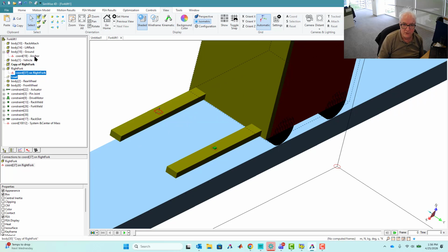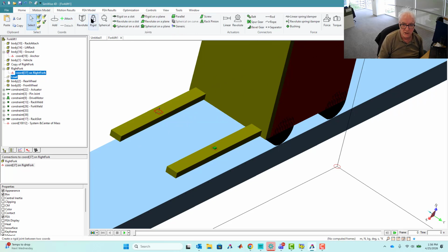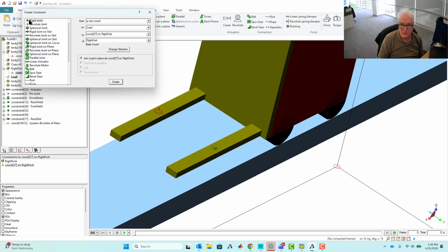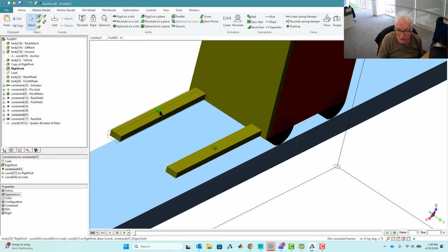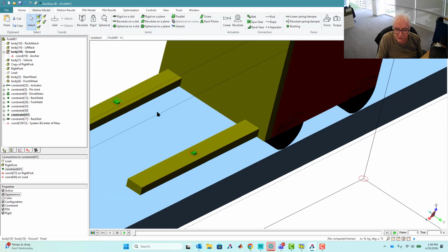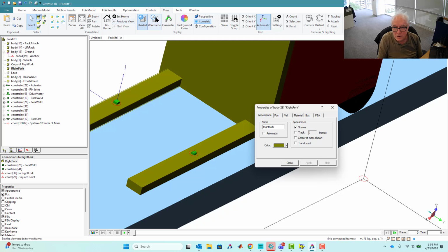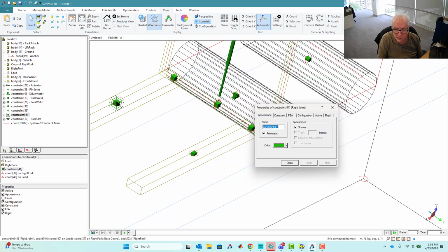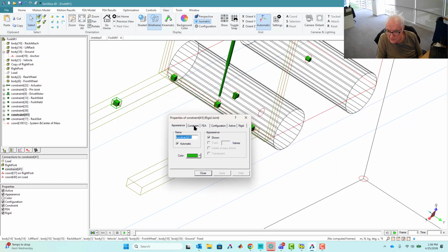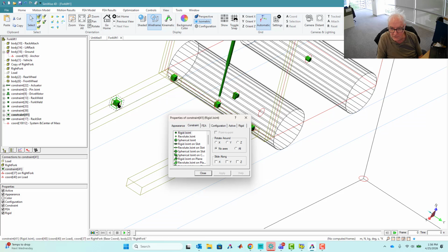So anyways, with those two selected, let's go motion. And again, I like this idea of creating a rigid joint because it gives you a good starting point. And so again, let's get it maybe to there. All right. And actually, this is what I'm going to do this time. View, let's look at a wireframe, and you'll see all this really well this way. All right. And so that constraint's right there, and we're going to allow it to rotate about all axes.